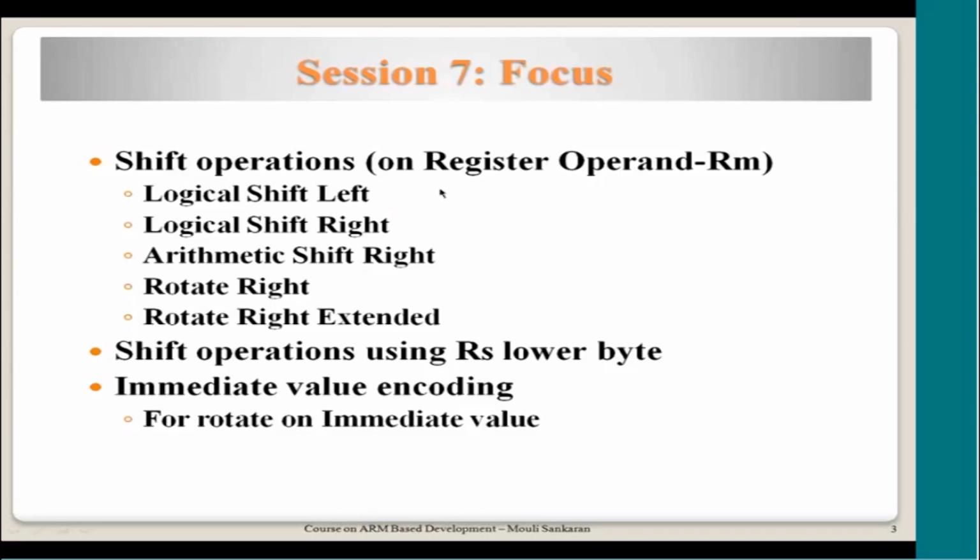In an arithmetic shift, the important thing we need to pay attention to is the sign bit of the value. All of you are by now familiar with 2's complement, I suppose. For example, suppose you have a 4-bit number 1 1 0 0.